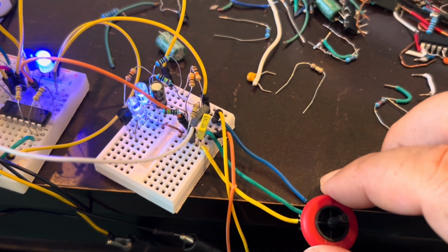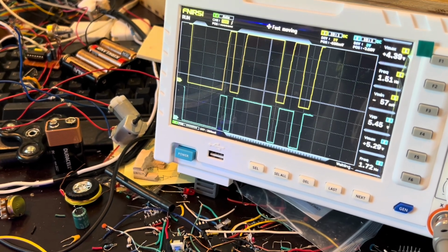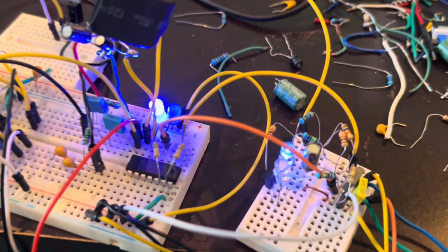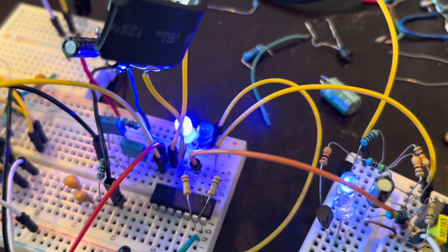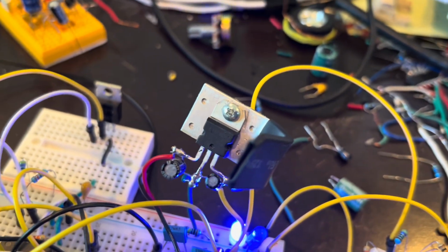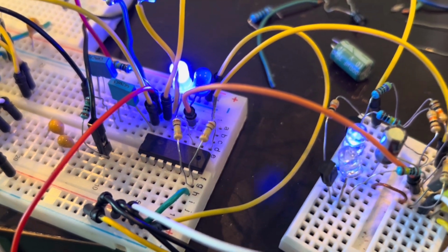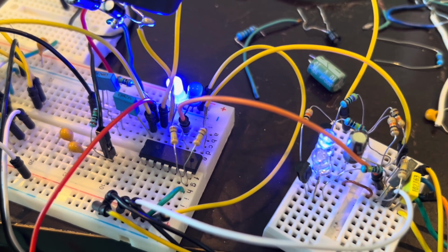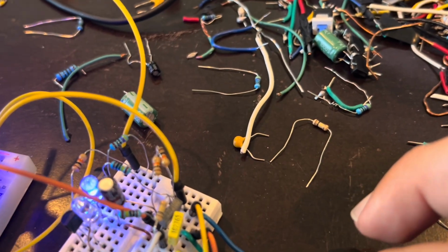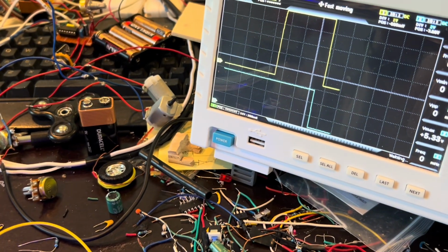So using this logic, what I've done here is I've connected this to a D flip-flop. This is basically powered off of a 5 volt supply through a voltage regulator here. It's a 5 volt circuit, and this is a CD4013, which is a pair of D flip-flops. And the way I have it is the output from the A pin, which is the blue pin, the blue curve,